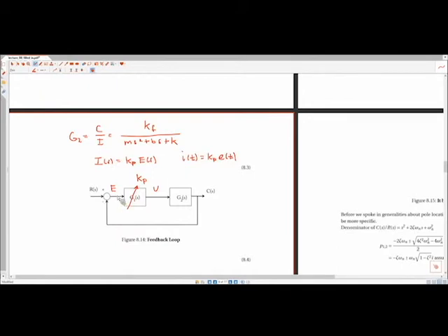That's your error. Multiply that by your proportion, Kp. So, for instance, this could be 1 or it could be 10 or whatever you design it to be. And then in this transition from the virtual to the physical world via digital to analog converters, the current to your system would then be Kp times E, right? So it basically says send out this value as your input to the plant, would be the idea.